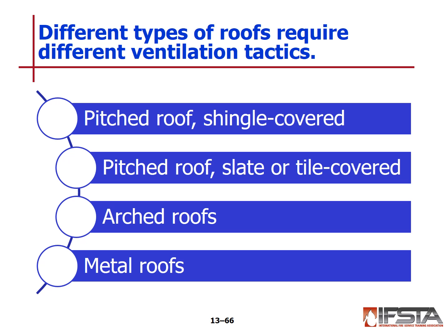Metal's becoming more prevalent in the area now, just because of the cost of it and the life expectancy of it. But in most situations where those metal roofs exist, they're directly mounted on top of the shingled roof. So you've got that small little void in there, so now you have to cut through the metal, and then you have to go ahead and make another cut through the old single shingle covered roof.